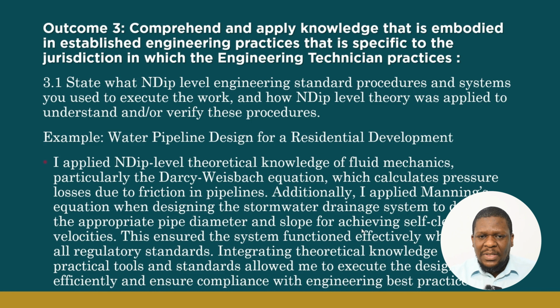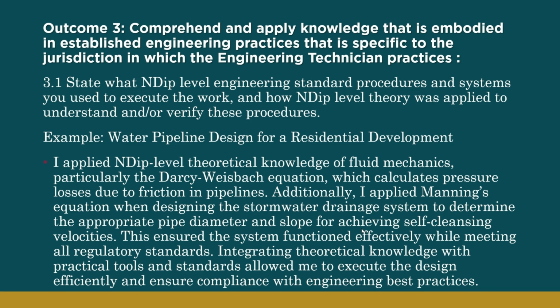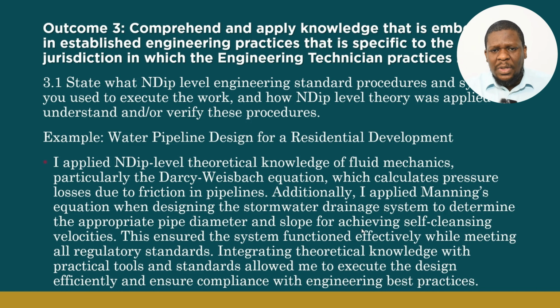Now, in continuation of the water pipeline design for the residential development, I applied the National Diploma knowledge of fluid mechanics or water engineering, particularly the Darcy-Weisbach equation. You are showing how you link your National Diploma knowledge to solving this problem, which calculated pressure loss due to friction in the pipeline. Additionally, I applied the Manning equation when designing, for example, stormwater drainage to determine the appropriate diameter. So you are linking the theory you learned at school and the solution you are presenting. This ensured the system functioned effectively while meeting all regulatory standards. Integrating theoretical knowledge with practical tools and standards allowed me to execute the design effectively and ensure compliance with best engineering practice.